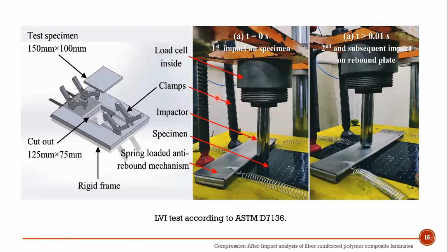So this was our testing setup for impact. Instead of going for hypothetical impacts, we created indentation on a specimen. This is a carbon fiber composite laminate on which we created quantifiable impact. We went for different impact energies of 10, 15, 20 and 25 joules on the composite material, and those specimens we then tested in the UTM for compression.